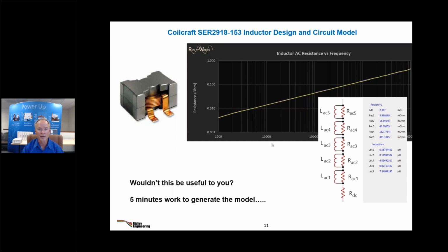Windings in parallel. Yeah, that's a good one. That would be an entire webinar. We actually did a paper on this that we'll be publishing fairly soon on our design center. In general, you don't want to put two windings in parallel next to each other and assume that nature's going to find the lowest loss path through those windings. It varies for every situation. But when you put two windings in parallel, and this applies to Dowell's equations and things like that, you can't assume they're going to current share, and they won't.